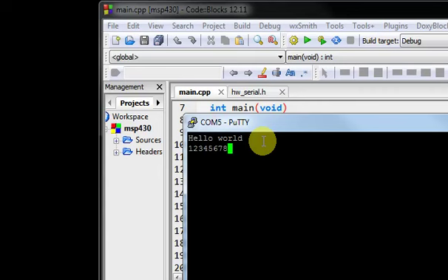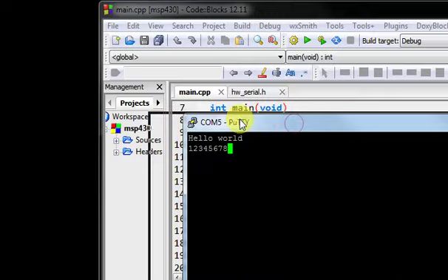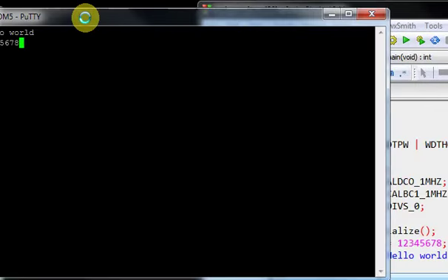So if something's not going as expected, I can just take a variable, spit it out over UART and see what's happening in the code to help me debug a project. Okay, again, something very simple. It's not going to replace actual disassembly debugging or anything like that, but it can be very useful for helping you determine what's actually going on in your code.